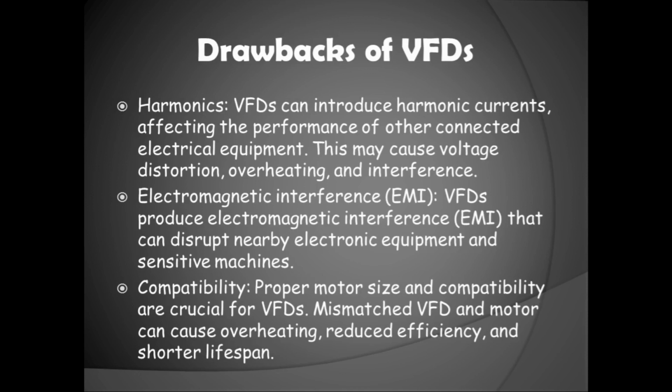Drawbacks of VFDs. While variable frequency drives provide many advantages, there are also certain drawbacks to be mindful of. Harmonics. VFDs can introduce harmonic currents into the power supply, which can affect the performance of other electrical equipment connected to the same system. These harmonics can result in voltage distortion, which may lead to complications including overheating, interference with delicate equipment, and reduced power quality. Harmonic filters or line reactors, for example, may be required in addition to other hardware to address this issue, thereby raising the system's overall cost and complexity.